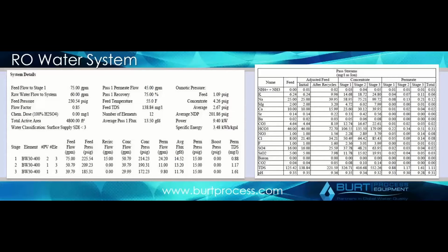And this is common depending on what the pharmaceutical requirements are. In those cases, they will hot water sanitize not just the RO, but everything upstream: water softeners, multimedia filters, etc. In those cases, the RO housing is typically stainless steel instead of fiberglass, and the RO membrane is designed for that hot water sanitization. An RO system cannot be fully drainable, but it can be flushed, obviously, to drain, and that's typically what they do when they hot water sanitize those types of systems.